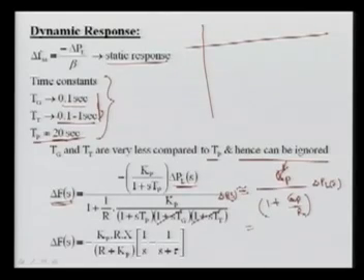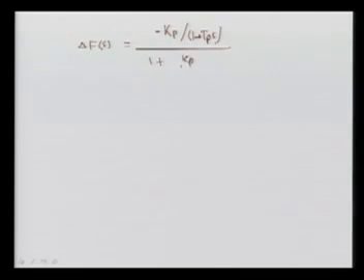Let us see how we are going to simplify GP, this function, and let us see this base. So what we are getting is the change in your system frequency, and now I have to write this Kp over 1 plus Tps, divided by 1 plus Kp into R into 1 plus Tps, and we have this change in PL.